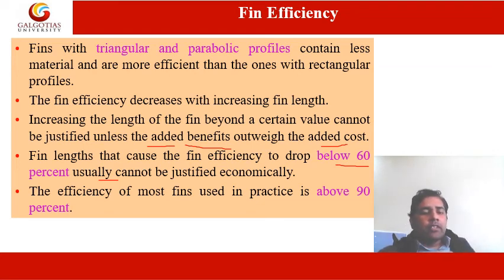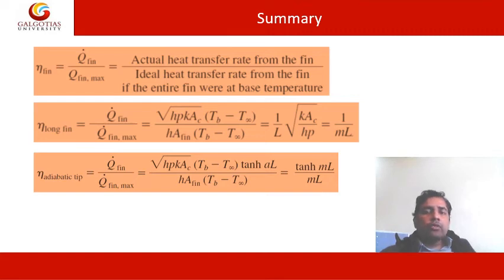Similarly, the efficiency of most fins used in practice is above 90%. This is an important thing that you should remember. Mostly we use fins with efficiency more than 90%. So this is what we learned today. We learned how to calculate the fin efficiency and what is the meaning of fin efficiency.